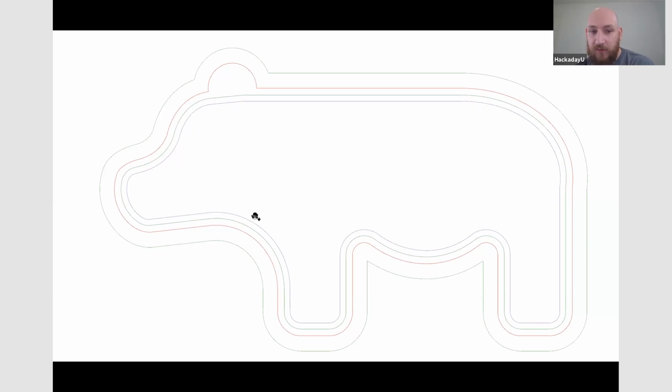And for the CNC file, I want to say that this inner blue line, I'm going to pocket cut on the inside, which means I'm going to cut all the material in the middle. And you set a height for that on the machining. So I set 2/3 of the stock, the 18 millimeters. And then next up, cut on the outside of this red line, and cut again 1/3 into the material. And then afterwards, pocket cut this green area, and then cut on the outside of the red line, which is a profile cut, which is going to cut out the shape.